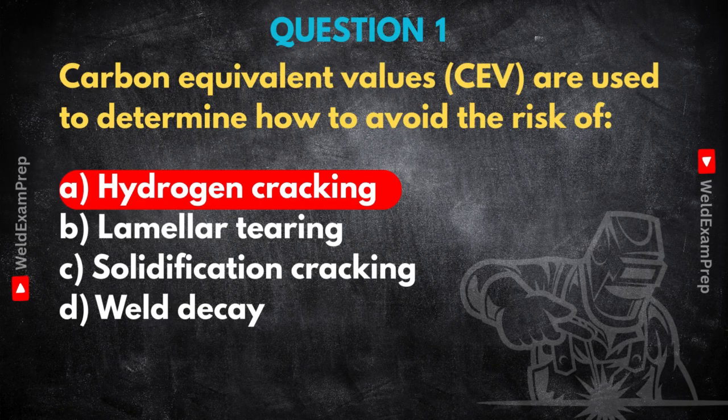Wow. Okay, so for you listening, the inspector, understanding CEV is almost like having an early warning system then. It tells you straight away what precautions, like maybe preheating before you even start welding or doing a post-weld heat treatment afterwards, might be absolutely necessary to dodge those potential cracking headaches. It's a critical preventative tool, really. Precisely. It guides your approach. Okay, that insight into the material science is just fundamental.